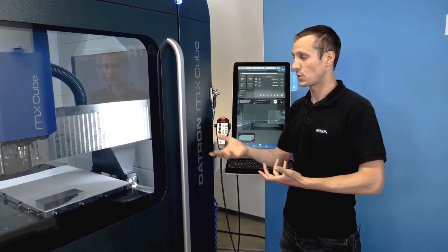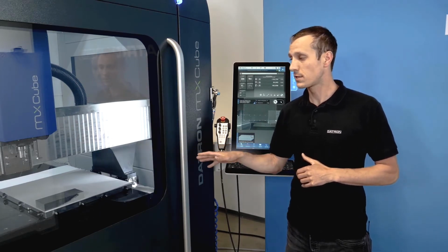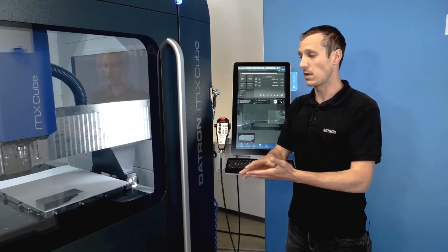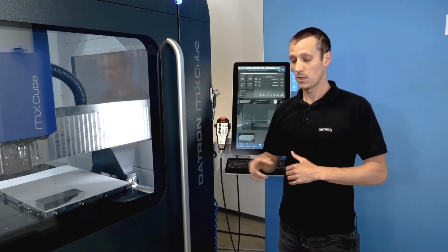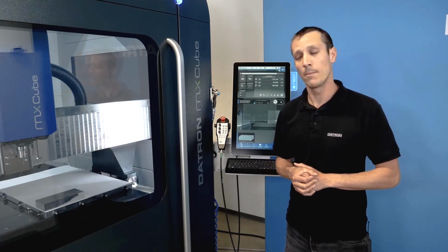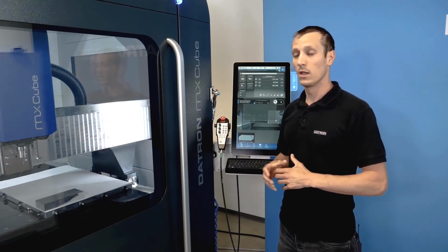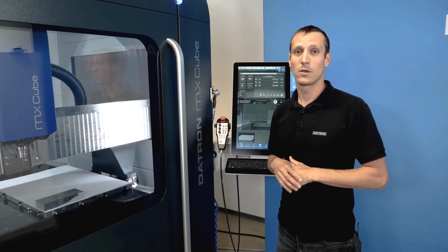So let's just imagine you have a part which is being cut out on the vacuum first, and then you need to flip it and realign it from the second side, and you want the features to match and to have everything in position. You just need the probe. You can use the camera, or you can integrate the cycle in your automatic program, and the machine will set the origin right where it should be.